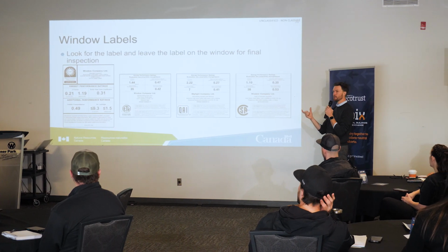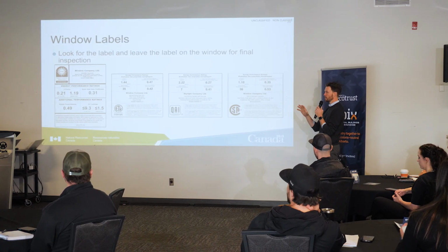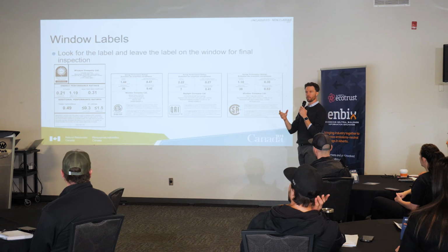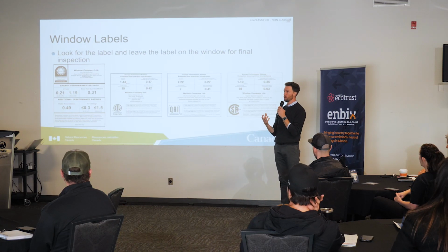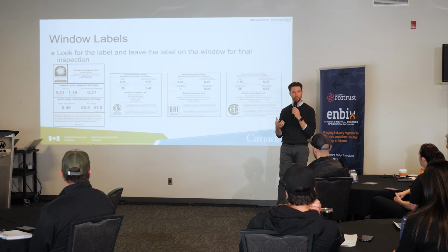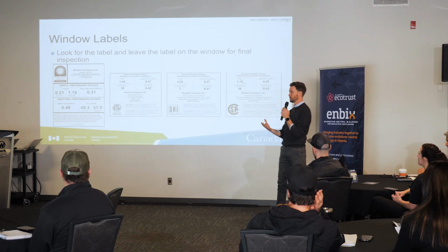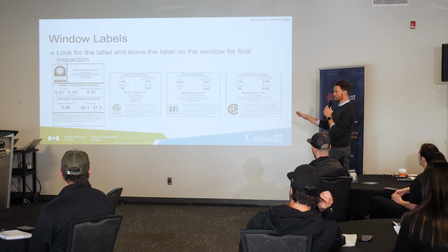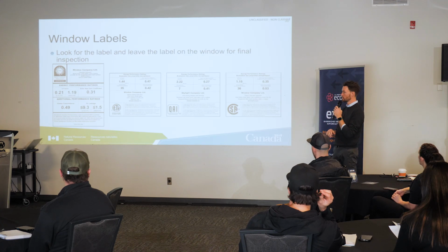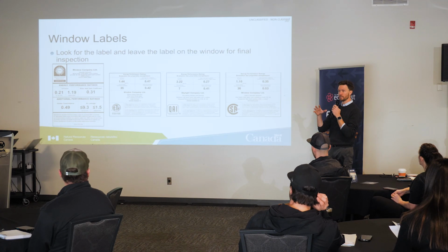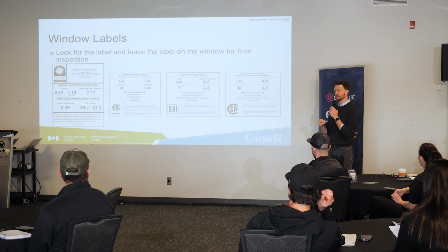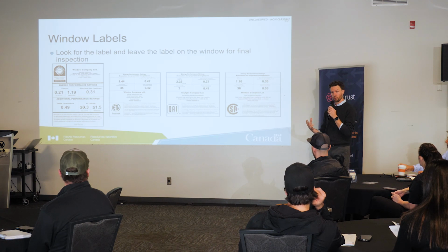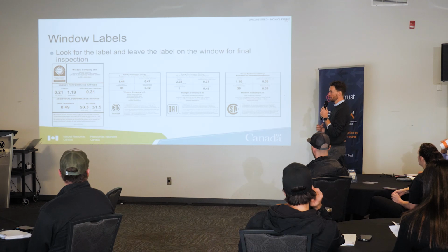Energy rating is very useful to get you in the ballpark, because what they tried to do with energy rating is come up with one number that gives you a sense of the quality of this window from an energy performance perspective. It's used in Quebec extensively to select and supply windows. But the takeaway I would really like you to have from this session is it's not the whole story, and you have to look at the other numbers on the label as well.